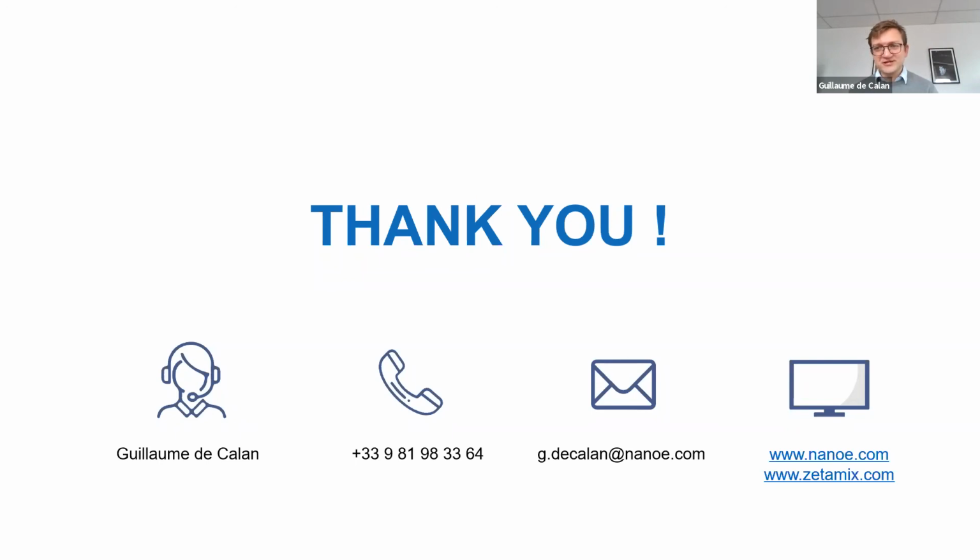That applies to a geometry you have already done at least once. That means repeatability. If you print a completely new geometry, you may have deformation you have not anticipated, you may have other things coming in. So it's not the most precise technique. And anyway, sinter-based printing has a limitation on precision.